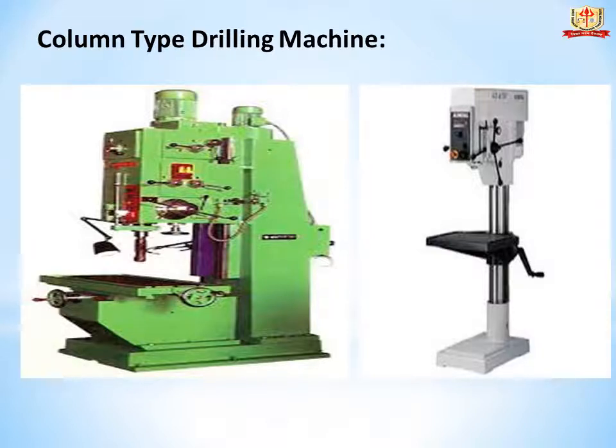Work table of machine may be moved up and down to accommodate job of different size. Work table can also be rotated 360 degrees around the column. Column type drilling machine is provided with a power feed. Column type drilling machine is used for medium size hole.